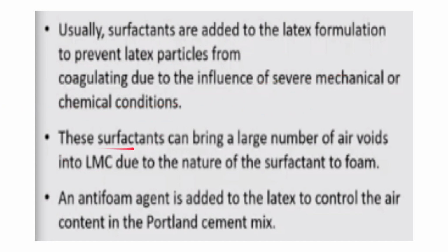These surfactants can bring a large number of air voids into LMC due to the nature of the surfactant to foam. So although it is added for preventing coagulation, it has a problem that it can bring a large number of air voids into LMC. So for preventing this, an antifoam agent is also added to the latex for controlling the air content in the Portland cement mix.